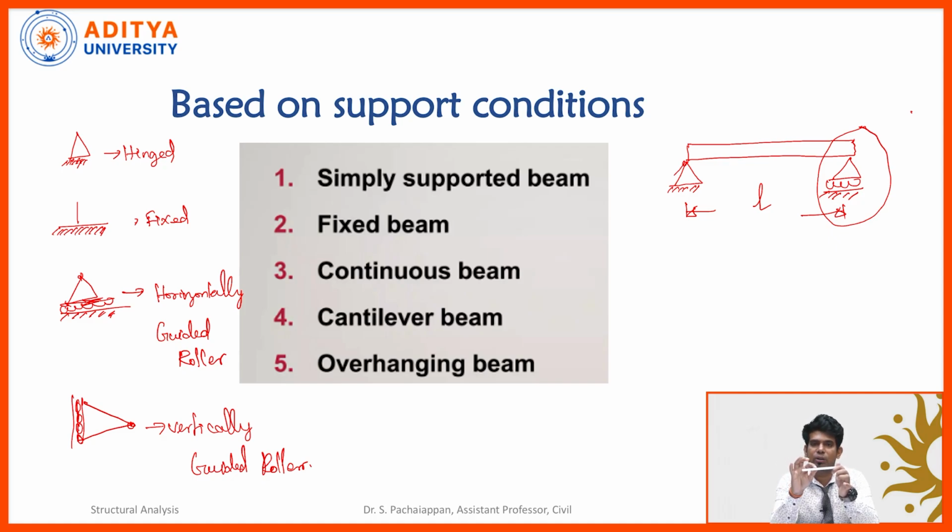That stress is going to create internal forces, which will cause material deterioration. So, we allow the beam to move in the right-hand side direction if it is subjected to elevated temperature. Generally in beams we neglect the axial forces because they are significantly less compared to the bending moment and shear force. That is the reason we are neglecting them.